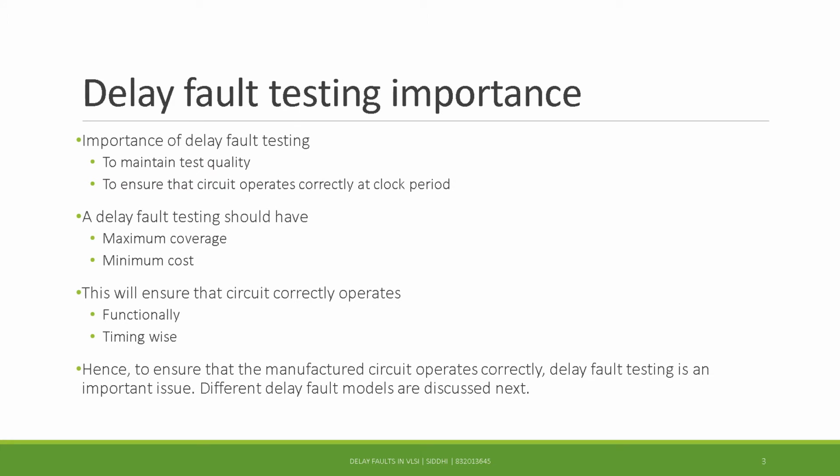To maintain test quality for speed-related failures, delay testing is gaining momentum due to growing density and increasing clock rate of chips. The purpose of delay testing is to ensure that the circuit operates correctly at the given clock period. A testing methodology which has maximum coverage and minimum cost needs to be explored. This will ensure that the circuit operates correctly both functionally and timing-wise.